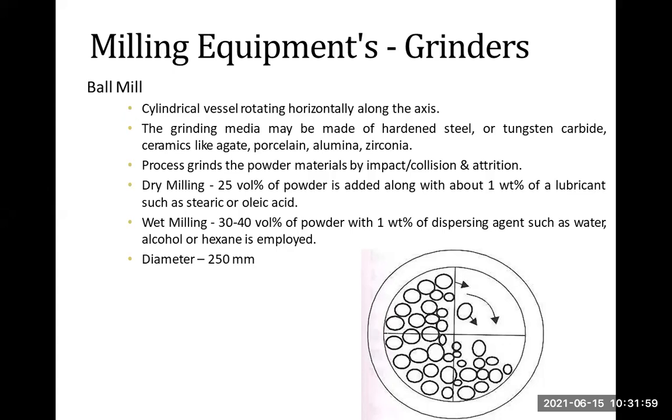For this, I'm going to take an easy example. I think you have seen the coins that we use. Initially they are pressed out, a press is used, and the coins are taken out. The end portions have to be trimmed or ground out. You cannot hold each and every coin to grind it. So that's why they use this ball mill. In this ball mill, they add the coins and certain additives like grinders, and it will be continuously rotating.